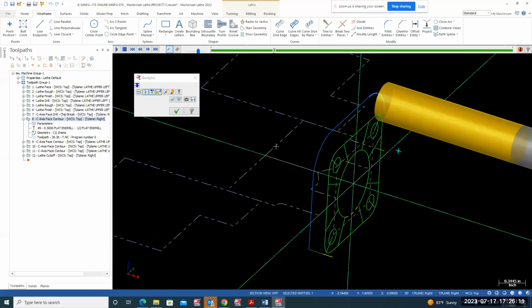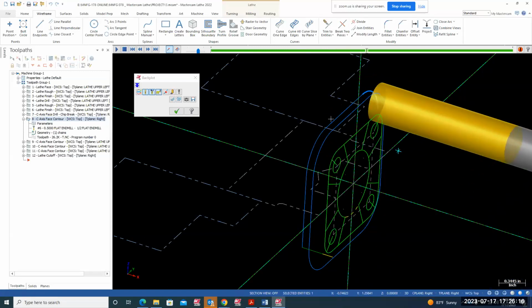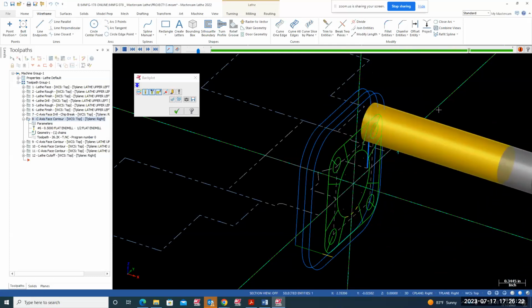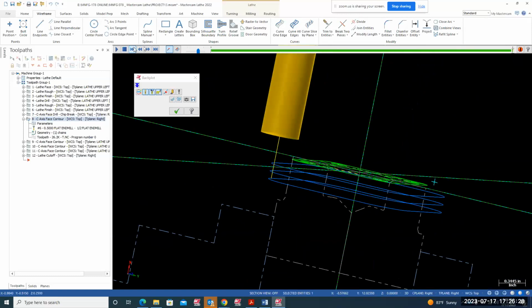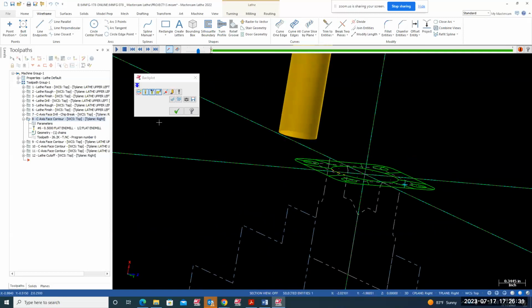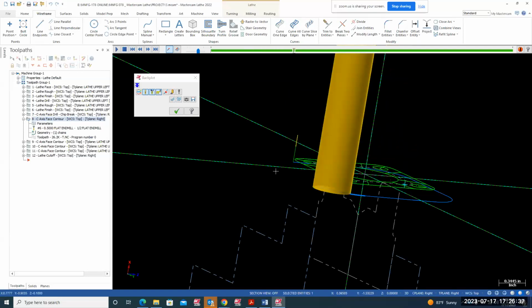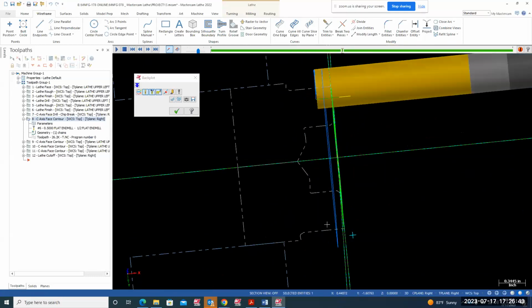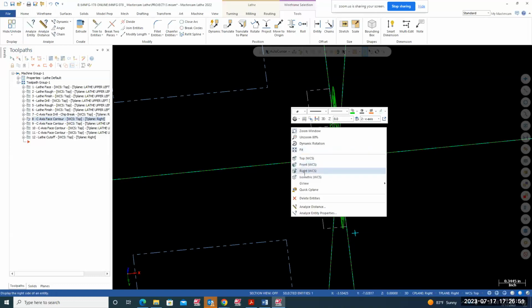So now your spindle is going to sync with your X and C axis. Your tool now, this guy right here, the yellow tool, is turning at 2000 RPM. It's working just like a mill. If you look under mill, it works like this, same thing. Looking from like that, it works like the mill. But it's cutting on the lathe on your right hand plane, just like this. That makes sense? I'm going to go ahead and draw this so you guys can see it. So let's go to the right plane here.